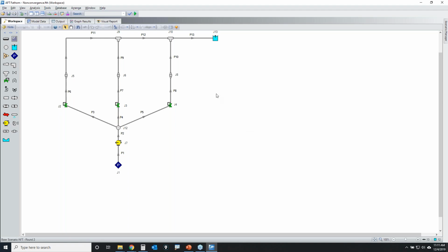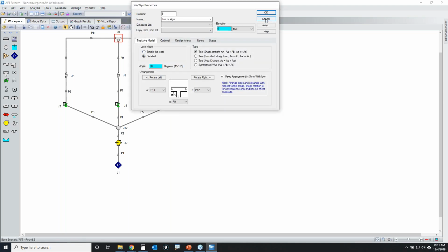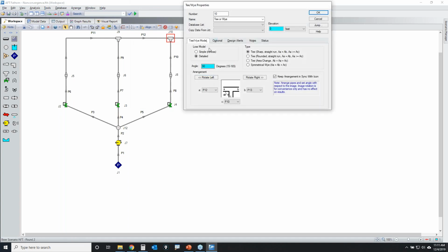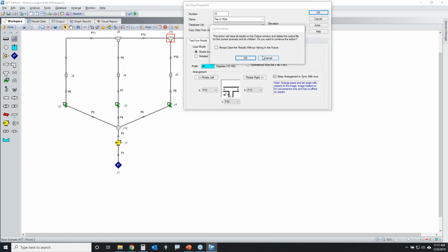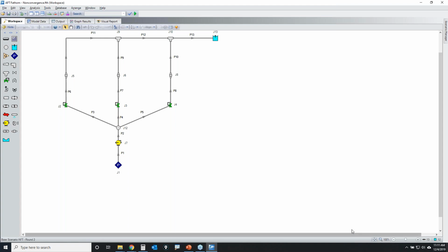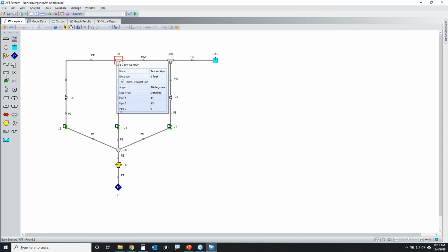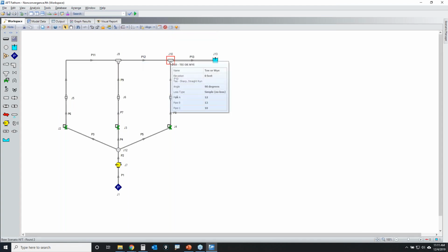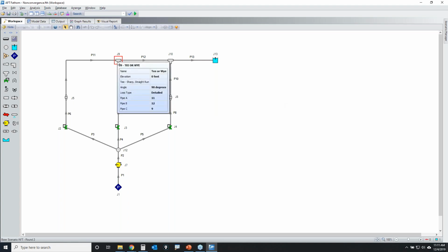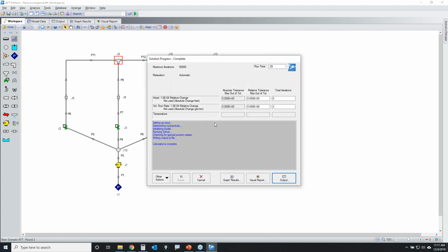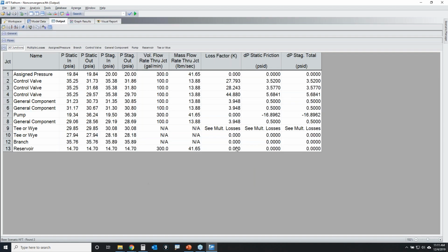Now, if you have to massage your model to convergence, maybe I don't want to change each of my T's to detailed altogether. Maybe I might want to do one at a time to ensure that it works. So if this is a detailed T and this is a simple T, what I might try to do to simplify the model is use the simple one first, run the model, and get convergence.